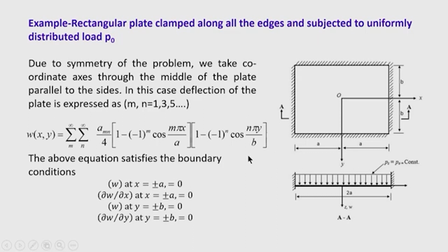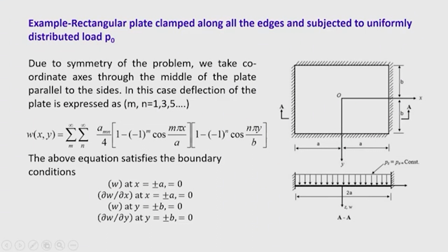Let us illustrate this problem with a single term expression, so that how the Rayleigh-Ritz method is used for solving the plate problem, you will be able to realize it, without unnecessary complication with the help of different terms in this series. First, let us investigate the solution procedure with the help of only one term of the series. Okay. Now, to use the Rayleigh-Ritz method, we first have to select a deflection function. Okay. Deflection function is selected. So, this process is over.